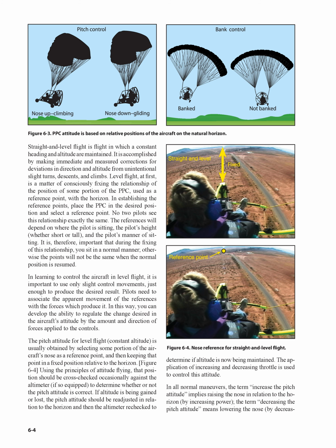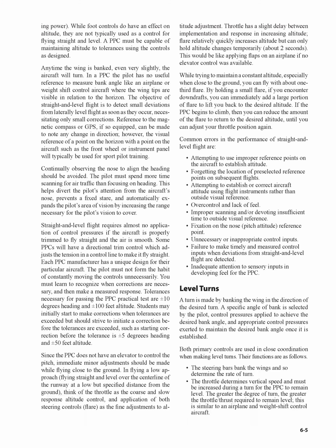In all normal maneuvers, the term increase the pitch attitude implies raising the nose in relation to the horizon, by increasing power. The term decreasing the pitch attitude means lowering the nose, by decreasing power. While foot controls do have an effect on altitude, they are not typically used as a control for flying straight and level. A PPC must be capable of maintaining altitude to tolerances using the controls as designed.